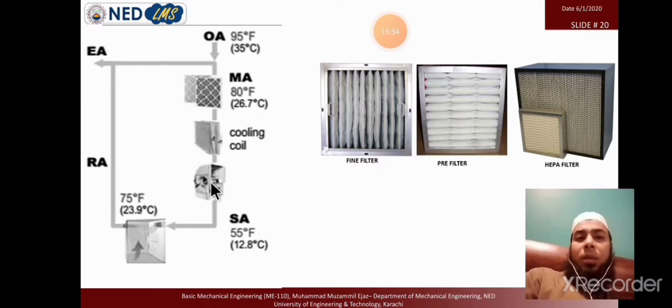But we do not shut off this blower, because in a closed environment you see that we don't have any fans. We also need to maintain the air movement that we already studied in the previous slides, where a person should have air movement to have a comfortable effect. Similarly, in the split AC indoor unit, when it reaches its set point, the blower does not shut off, but the compressor behind in the outdoor unit stops. So it just recirculates the air but does not cool down the air.